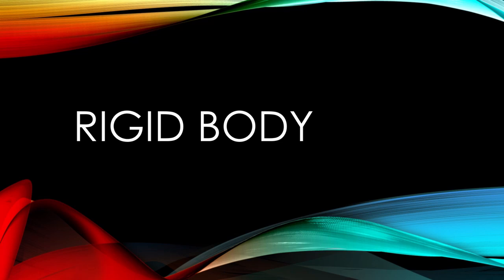Rigid body. A rigid body can be considered as a combination of a large number of particles in which all the particles remain at a fixed distance from one another, both before and after applying a load. This model is important because the material properties of any body that is assumed to be rigid will not need to be considered when studying the effects of forces acting on the body. In most cases, the actual deformations occurring in structures, machines, or mechanisms are relatively small, and the rigid body assumption is suitable for analysis.